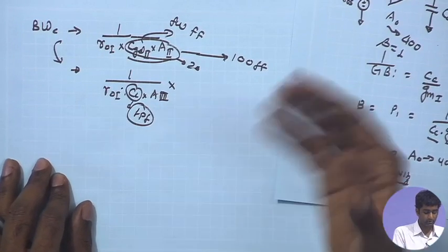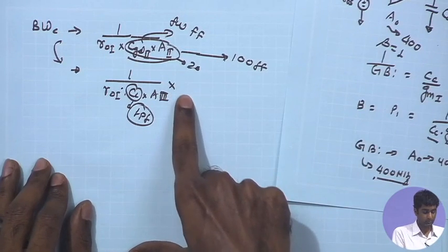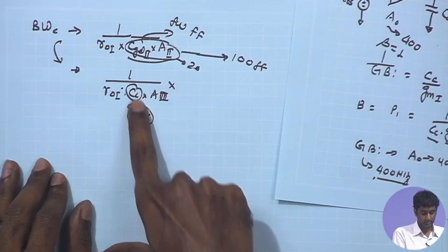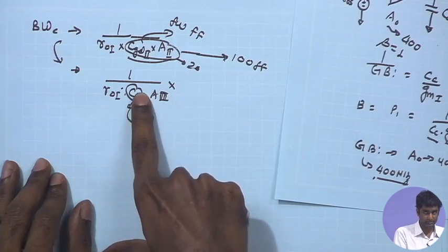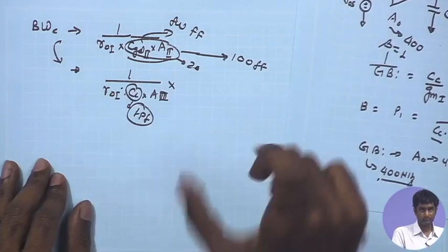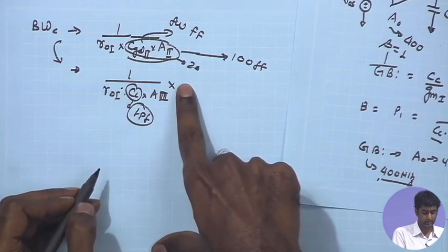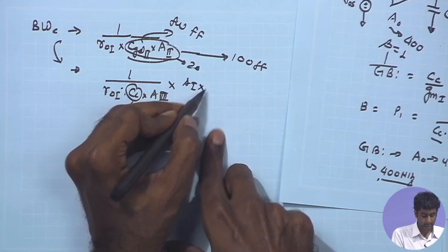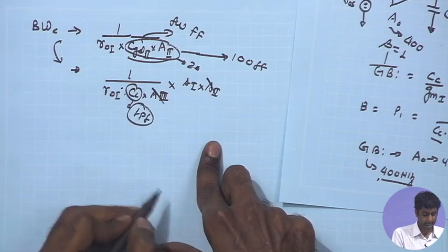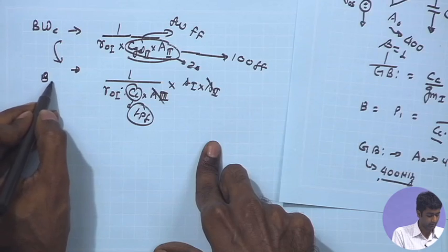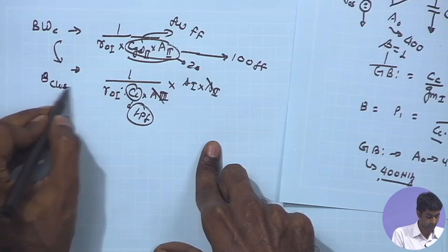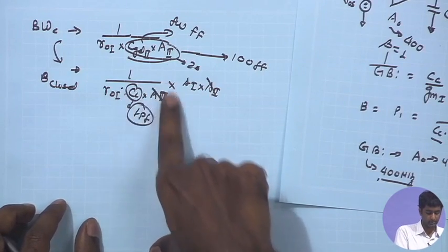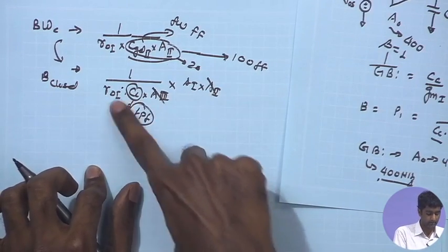But apart from that, we also have the overall gain, right. So, this is the open loop bandwidth given by the first pole and the Miller multiplied CC, the compensation capacitor. This is multiplied by the 1 plus A beta factor. Once again, A beta is approximately equal to A, which is A1 times A2, where A2 gets cancelled, and therefore the closed loop bandwidth is going to be A1 times this number. So, you are going to have A1 A2 times this number.